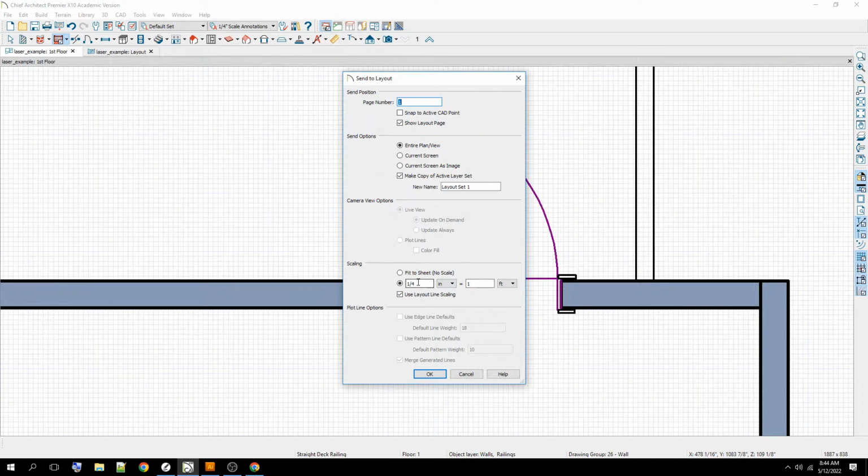Down here is your scale. Remember we talked about it and I said we were going to stay within the imperial measurements for this specific project. And some of you said, I'm going to do a 1/16 of an inch to indicate a foot. Or I'm going to do 1/8 of an inch to indicate a foot, right? So for every inch, that symbolizes 8 feet, right? You could say 1/4 of an inch equals a foot. So this is independent of your personal model. For example, if your building is huge, you're going to have a smaller number here than if your building is small.